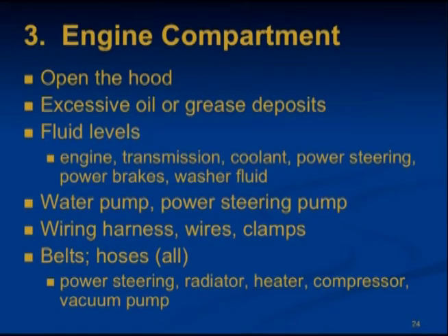Now, check for excessive oil or grease deposits. Check for fluid levels. Engine oil must be checked when the oil is warm. Check the transmission fluid, which should be done when the fluid is cold. Power steering and power brake fluid if applicable. Pull out the dipstick, wipe it clean, insert, remove, and check the fluid levels. Add fluids as needed. Make sure that the coolant reservoir fluid level is sufficient and the cap is secure.